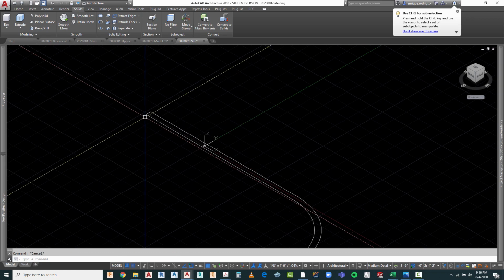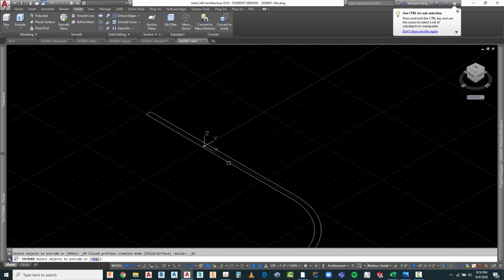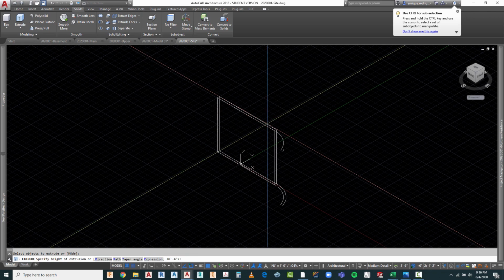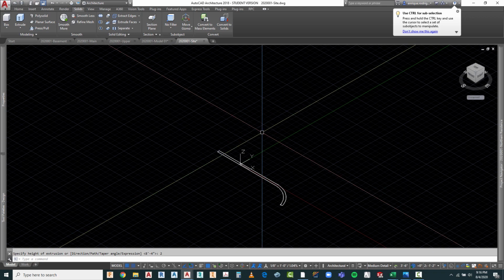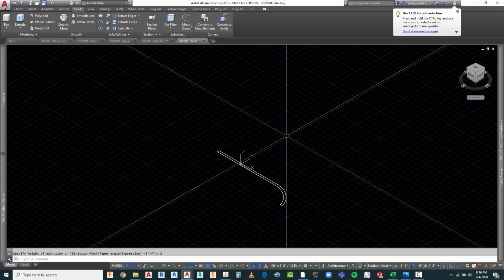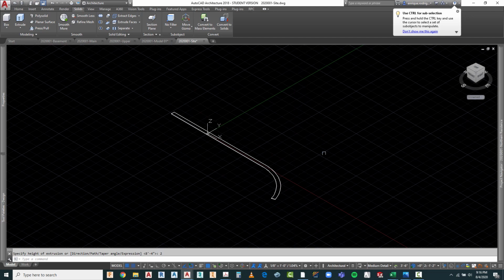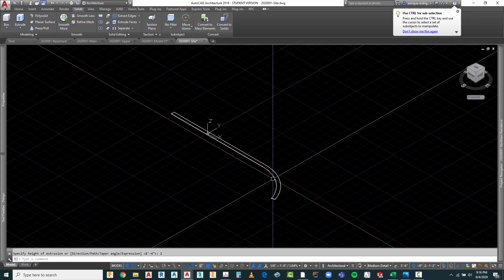That part looks good. Now let's go ahead and extrude. The distance that we're going to be extruding is, I'm going to go in a vertical direction this way, and that looks like it's extruding okay, but I'm only going to do 2 inches. The reason I'm doing the 2 inches is because our drawing plane here is at -1 foot 2. And remember, the top of our garage and the top of our walkway, our front porch, was at -1 foot. So the differential between those is only 2 inches.